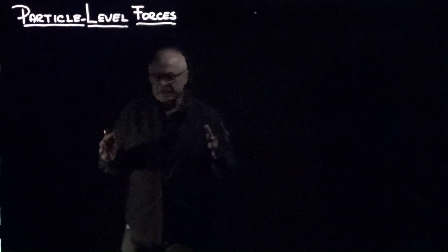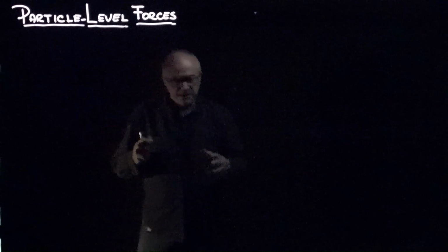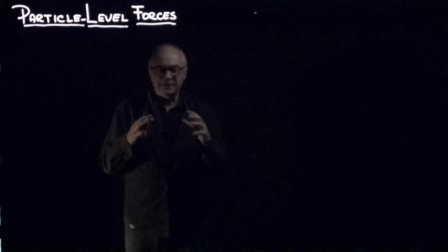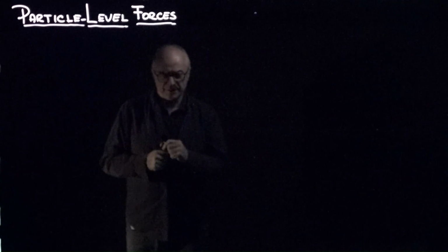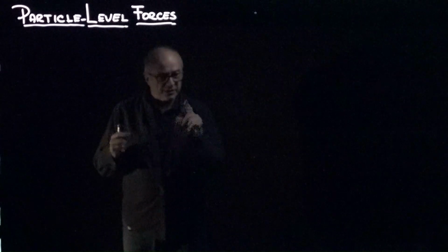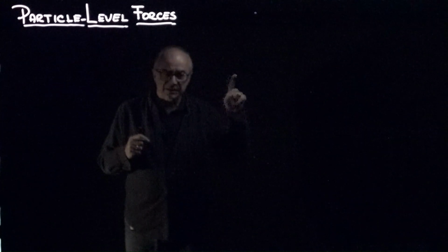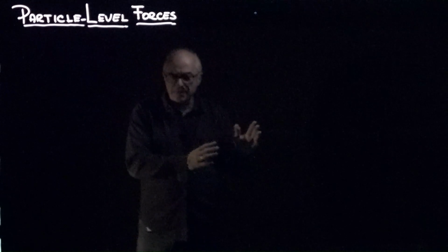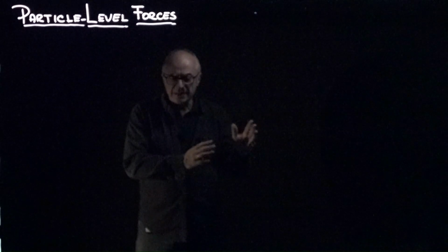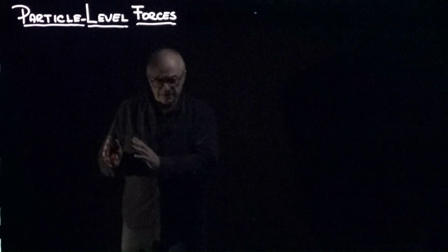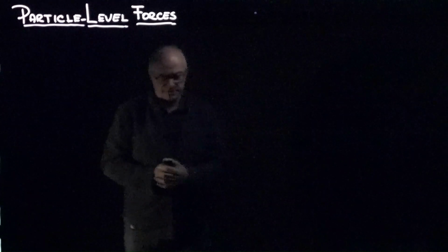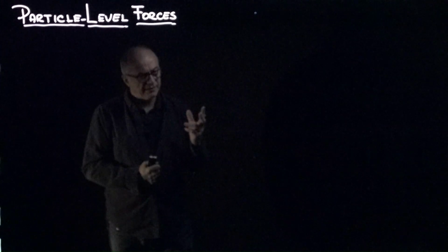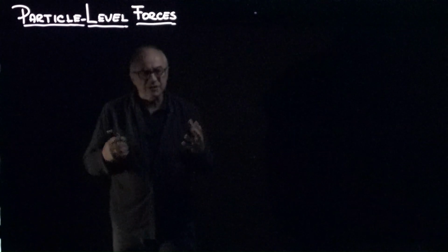A foundation settlement, or a landslide, or a tunnel collapse means that particles are moving. Displacement is 1/2 acceleration delta t squared, and acceleration is coming from Newton, F equals ma. That means that if there was a displacement, there was an unbalanced force. Then we have to ask, what are the forces that are acting on particles?